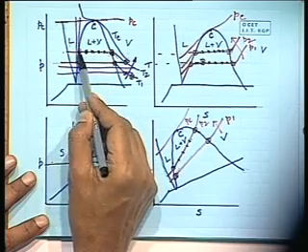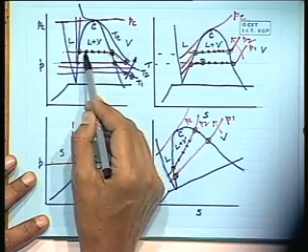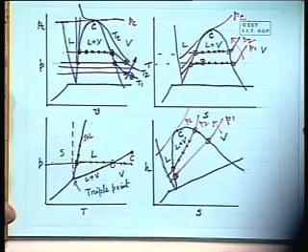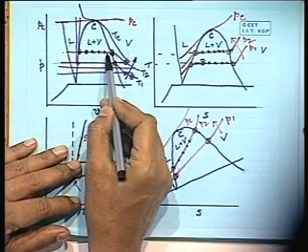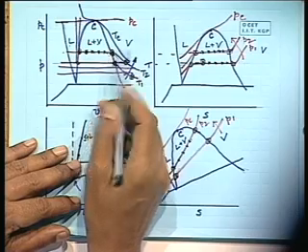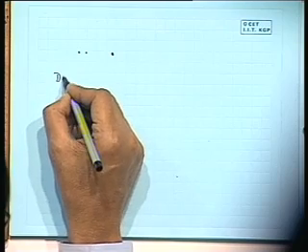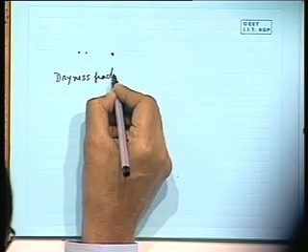This is a pure component, a single phase. These are pure components, but these are a mixture of two phases. Clear? So to specify any property for these state points, we will have to specify the mixture composition, and that is known as dryness fraction.